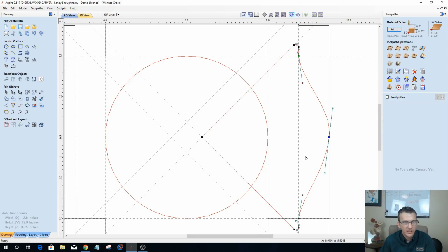Oops. Always select the one you're aligning to first. Hold on a second, like a goofball. Let's undo that. Select this one here first, and then this one, and then hit the letter X on the keyboard. And I could pull those two into alignment if I need to, to help me with my shape. Now on this one, I want these arcs to be the same. I don't want them adjusting like this. So on this midpoint, I am going to pull this and align it straight up with my rectangle out here. I don't want it crooked like this or anything. I need it aligned straight.